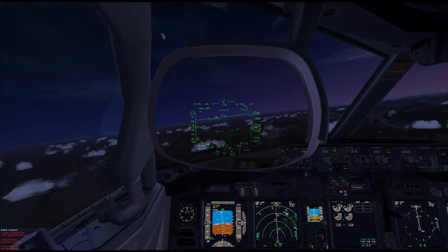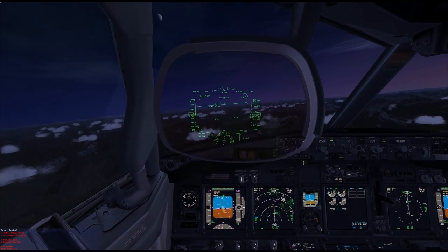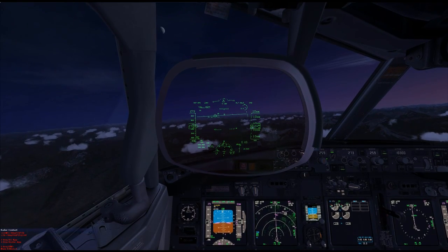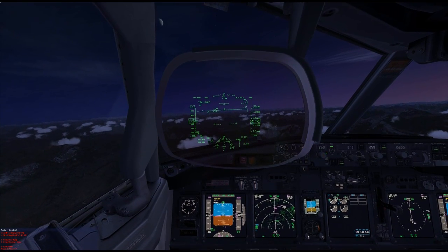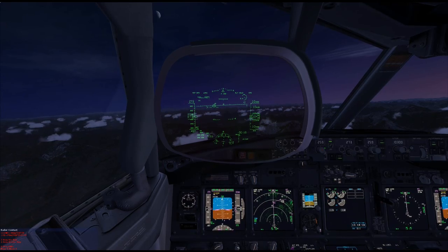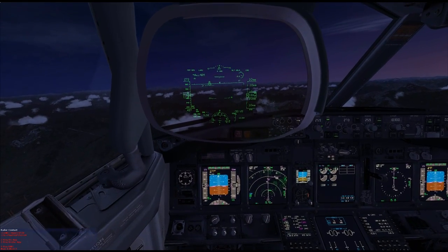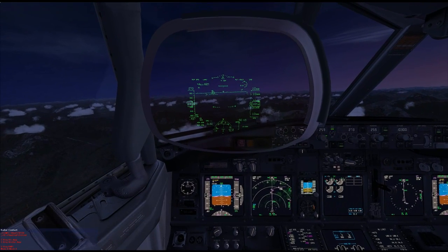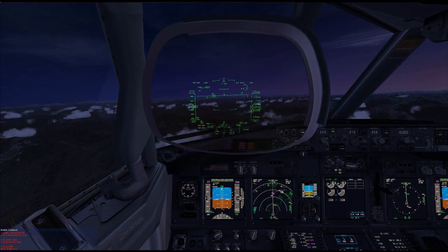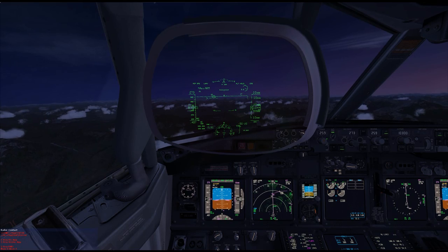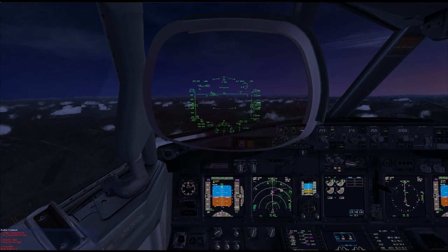Okay, we will be arriving by ATC vectors. We can expect an RNAV approach. Landing runway condition is dry. Anti-ice is not required. Landing flap will be 30. Auto brake we will use level 3. Engine bleeds will be on. Minimums will be 200 feet. Any questions? No questions. Approach brief complete.